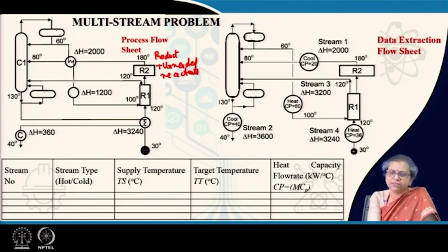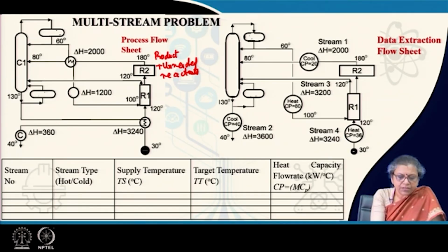They have, more or less, I assume, sufficient difference in the relative volatility. So, I would take up distillation as the process. So, this particular stream I introduce into the distillation column. Another additional stream is also introduced into the distillation column from the reactor point.